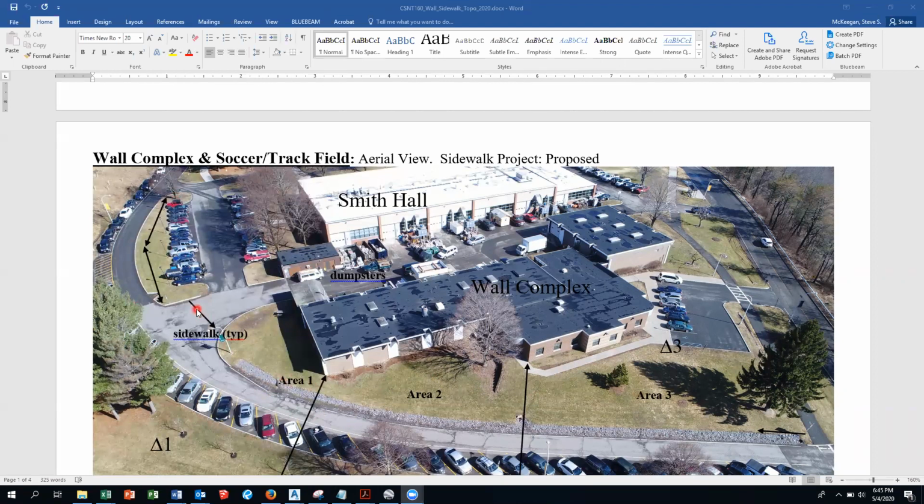So the sidewalk plan would be to connect, say, maybe put in a sidewalk right here. So you'd have like a little diagonal crosswalk, put a sidewalk in here. That's easy enough to do. Put a crosswalk across here. And this is the nasty pinch point. There's two issues here. This one right here, and this one, which is a storm drain. There's actually a storm drain here and a storm drain here. So that's an issue over here and over here.